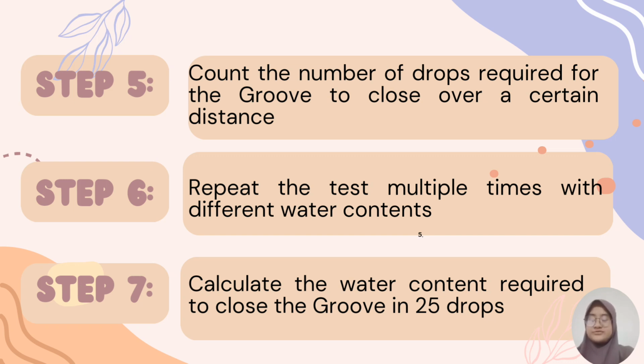Next, step 5, we need to count the number of drops required for the groove to close over a certain distance. Step 6, repeat the test multiple times with different water content. Lastly, calculate the water content required to close the groove in 25 drops.